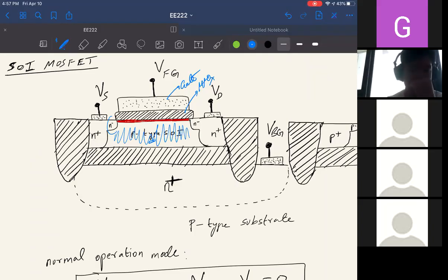So basically, you have this N- region near the channel because you want to reduce the electric field in this PN junction, because there are some high field effects that happen if you don't do that. There's an N- region here, and then a heavily doped N+ region, which you see here. The contact is usually made to the N+ region because if you make contact to a lightly doped region, you'll have something called a Schottky junction, which prevents your current from flowing. So you always need to contact a heavily doped semiconductor, so that you make an ohmic contact, which allows current to flow in either direction without any barrier.